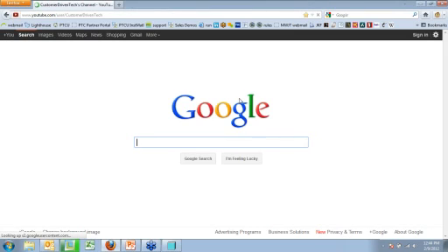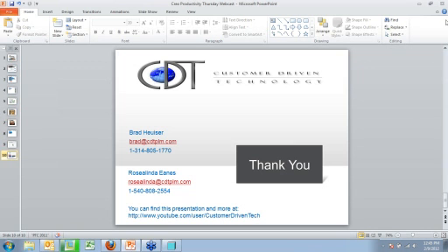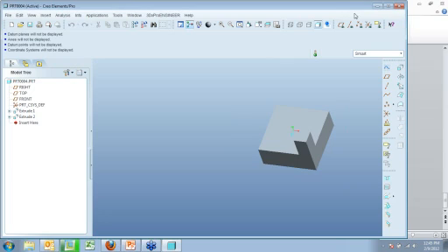We do have a couple of questions in the queue. Okay, all right, we'll go ahead and ask those. The first one is, wasn't that datum display on-off button in previous, earlier Pro/E releases? Well, I'll flip back over to Wildfire 5. Yeah, they do have these buttons here, and there might be another option in there to add another button that turns all of them on and off, which I know you can do. You can create custom buttons and do config.pro things, set them to map keys and stuff. I'm not sure if there was one button specifically that did that, but I guess the point of what I was saying was that it's right up front.